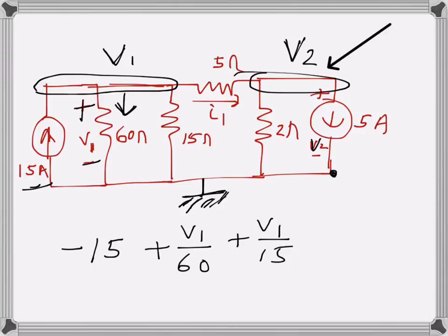And then we have the final current going away, which is also I1, but instead of writing I1, I will write it in terms of voltages. That will be better. The voltage here is V1, the voltage here is V2. The current is going in this direction, so the drop across 5 ohms is V1 minus V2. So V1 minus V2 is the drop across the 5 ohms resistance, divided by the resistance, 5. That's Ohm's law, that's the current.